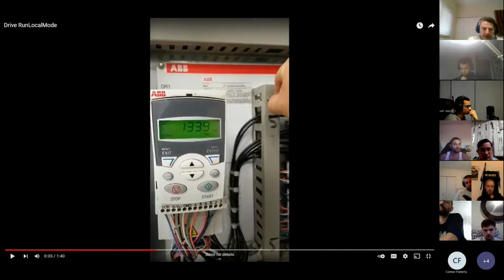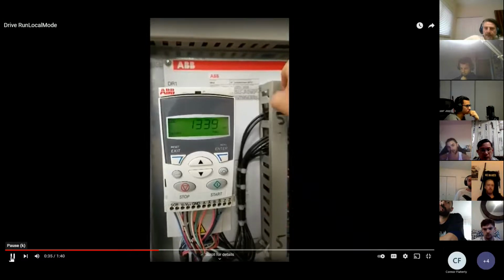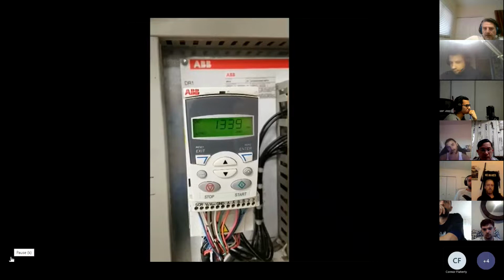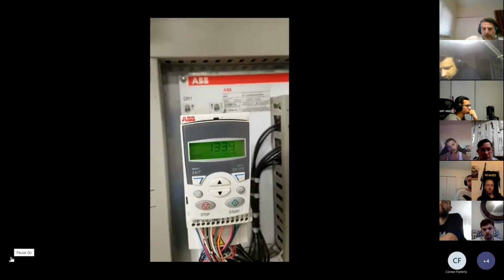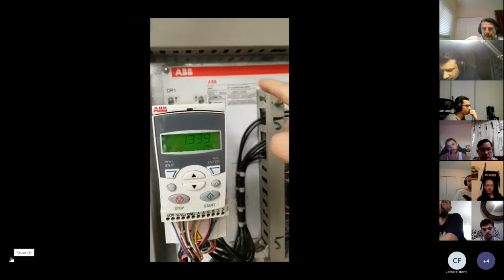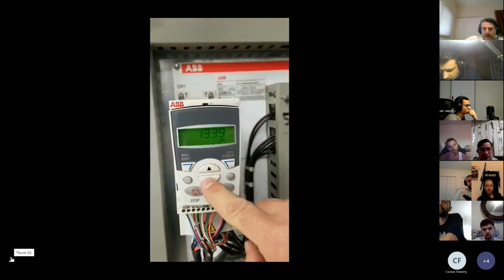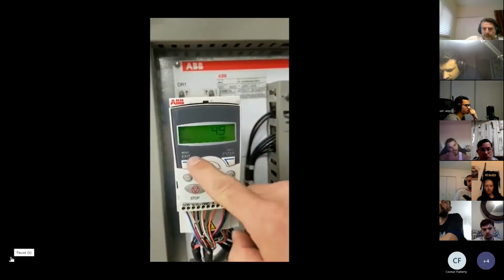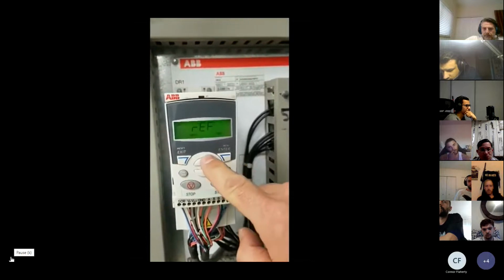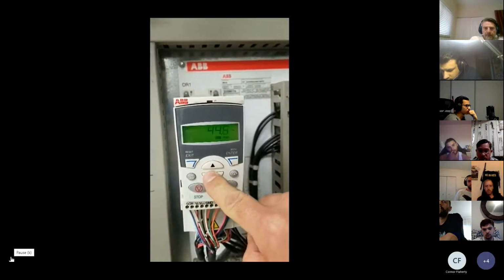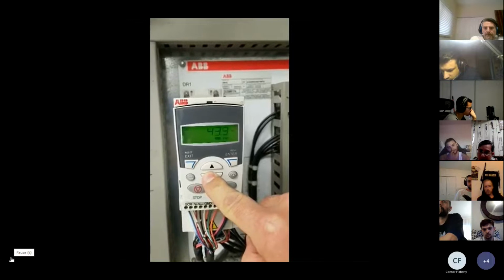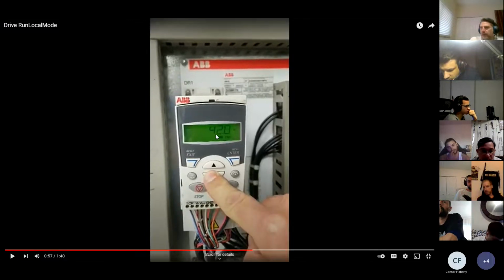And this is what I'm going to show you now to change the speed. I can lower or higher the speed. Well, actually, no. That's actually going to be on remote because it's not locally here. I can actually change the speed here right now. If I go to reference, press enter, I can lower the speed here. So the speed is actually in hertz here. Remember, it's a variable frequency drive. So now it's outputting 42 hertz. There is an equivalent RPM that was being displayed before. So now I'm going to use the up-down arrow keys here to increment the speed.